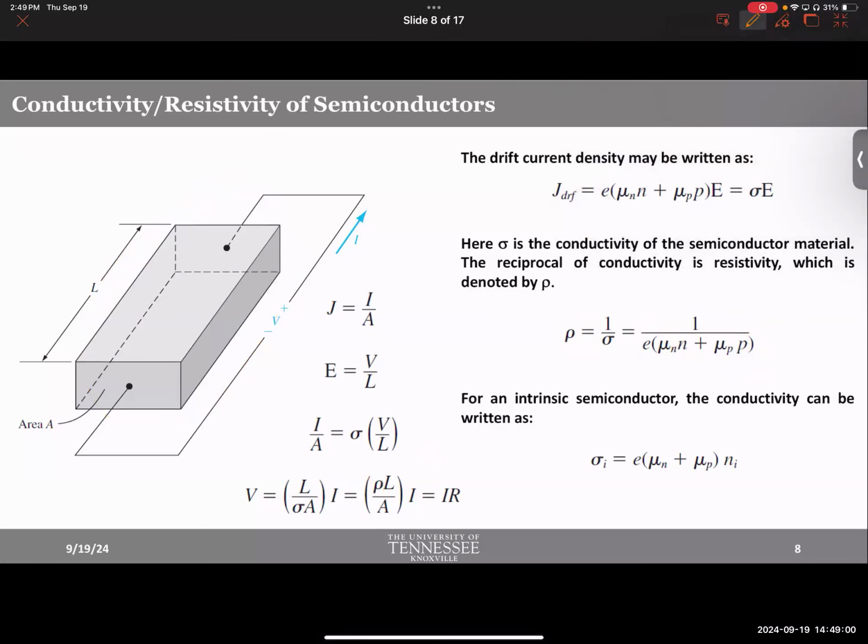So far, what you have seen is that the resistivity of semiconductors is a function of the number of electrons and holes in it. And the number of electrons and holes could be changed by changing the doping concentration, which is similar to changing a metal as well, because you're doping it during the fabrication process. But what you haven't seen yet, and you'll start seeing gradually when you start talking about devices, is that it's possible to change the number of electrons and holes within the same material by applying a certain voltage, or applying an external stimulus. So you haven't seen non-equilibrium yet. That's where we begin today, by the way.